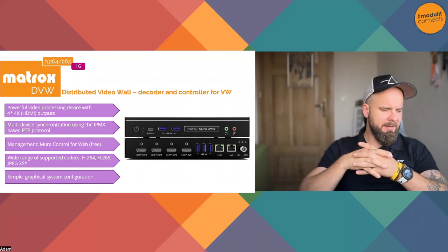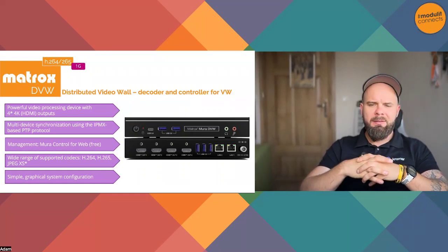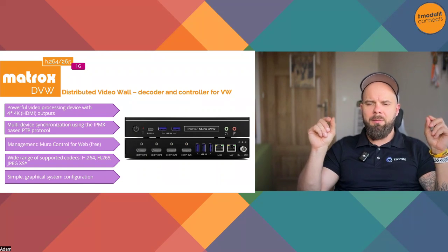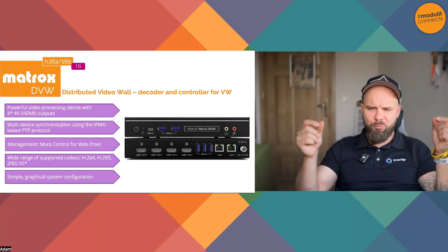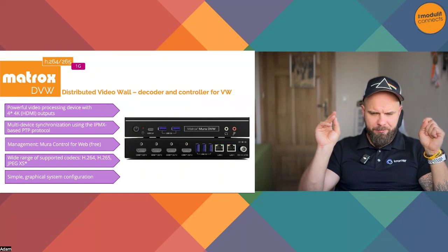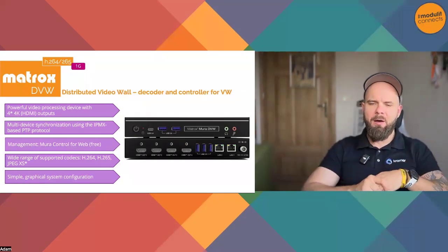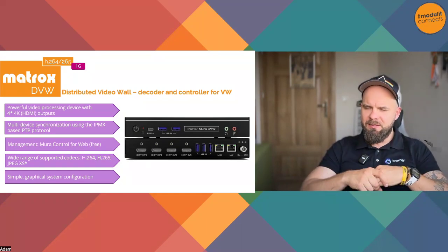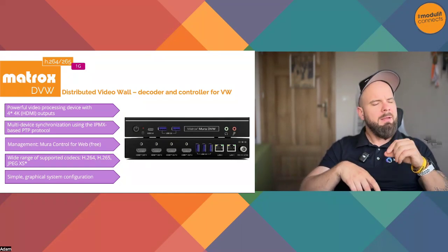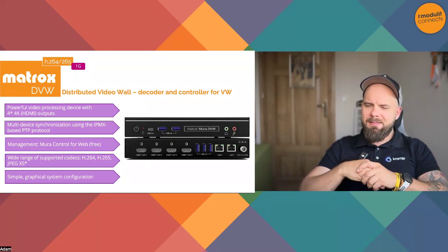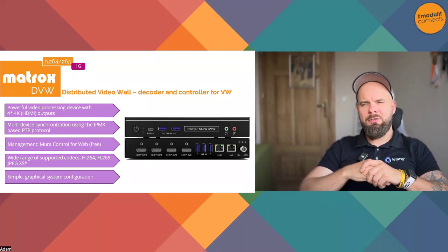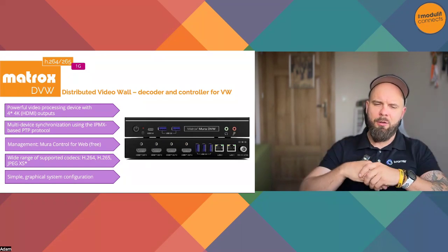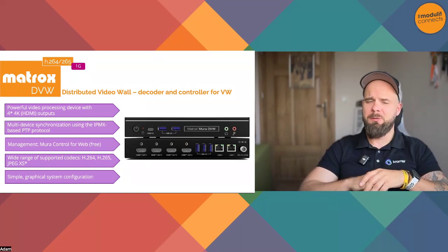The next thing is the device I call decoder and video wall controller in one box. Why? Because this is actually an AVoIP decoder with 4 HDMI outputs you can use to connect with the displays inside the video wall. LCD based, LED based, doesn't matter. Just use whatever you want, because this device allows you to do so many things with the signal.